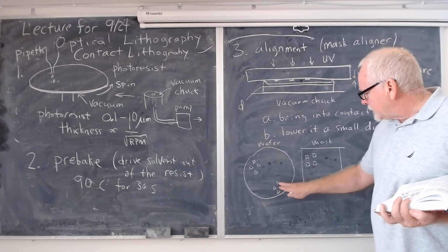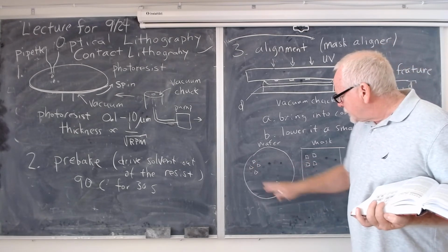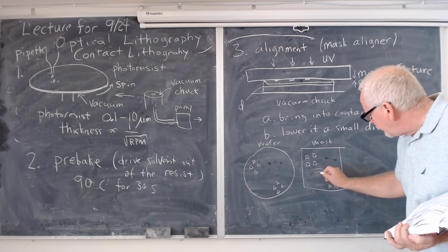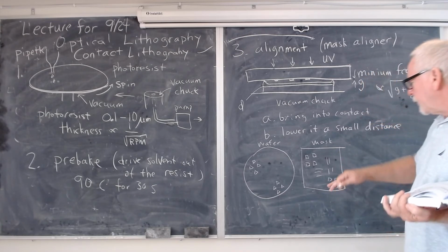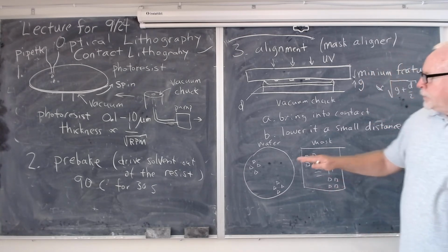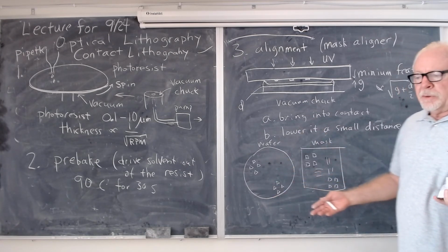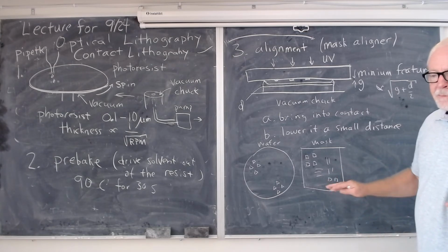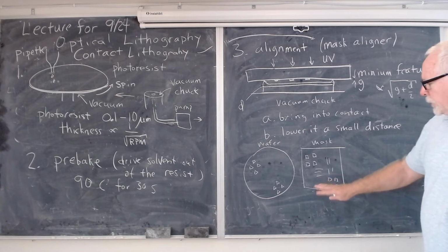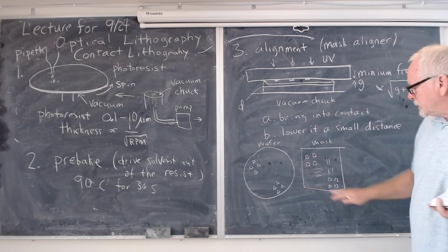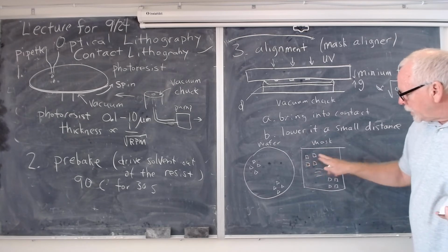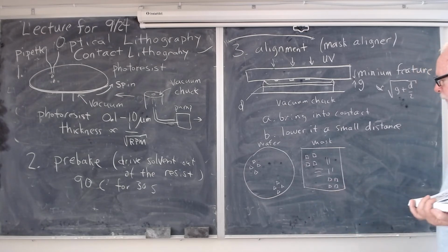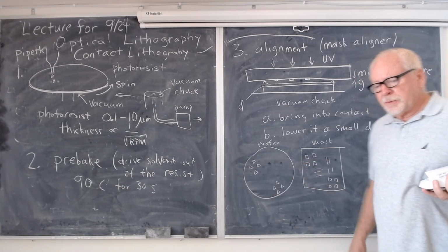And in fact, what I've drawn here is a very rough alignment mark. Usually it's a plus sign and then 4 squares like that. And so you would line things up. And then this mask might have some sort of device features that are your next step. Basically every photolithography step, you have a different mask. Sometimes if you're making small things, you can have the same mask and use different areas of it, but it's easier to think that each step has a different mask. And so each mask would have the alignment marks for lining up with the original alignment features that you put on the wafer, which are typically just some metal features you put down.